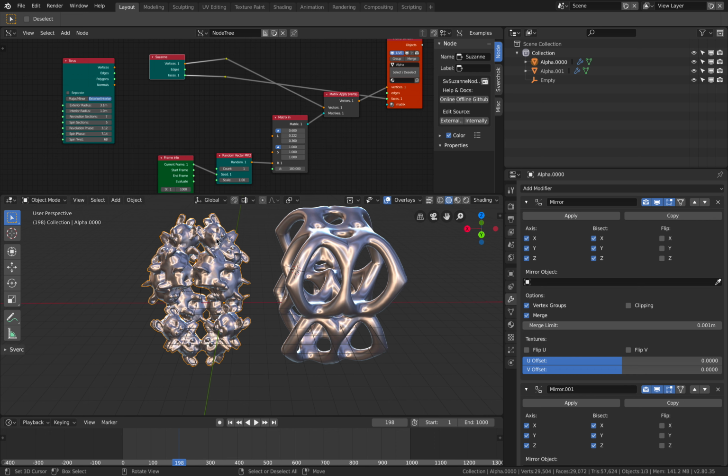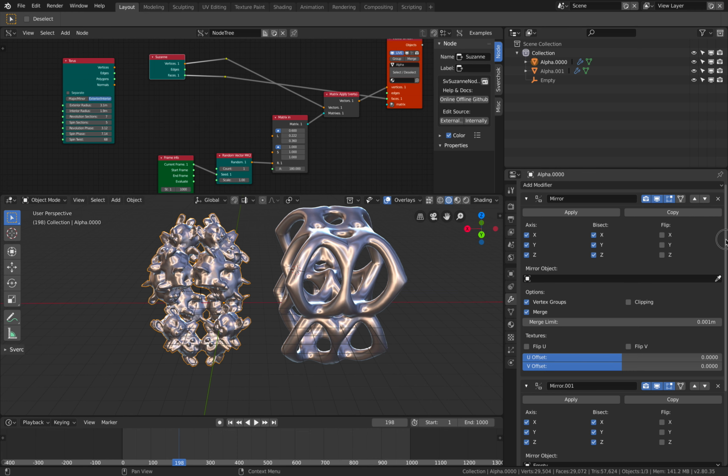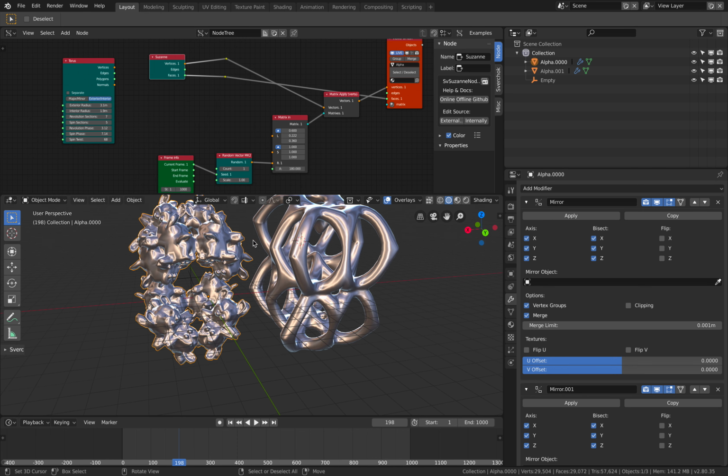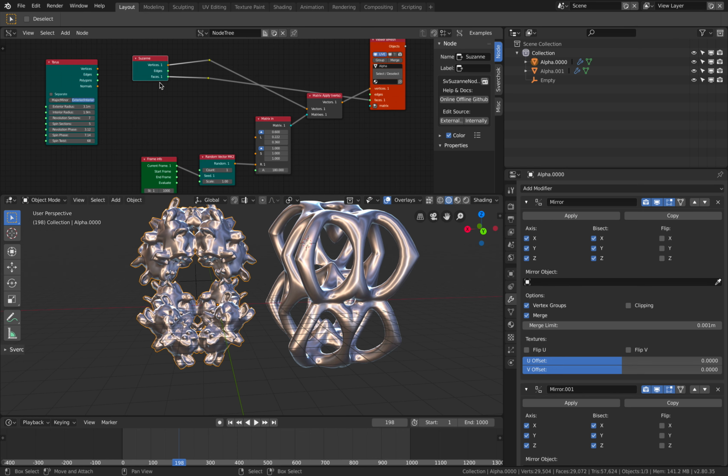So you go inside the mesh and modify the mesh, and then on top of that, the modifier, which is always like a post effect on a mesh, can work on top. So this one is almost like edit mode, and you're doing it procedurally. So it's really powerful.